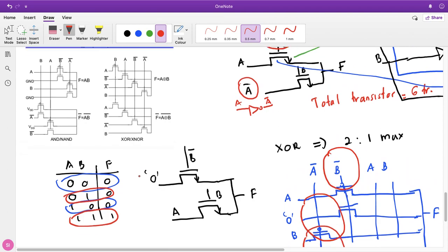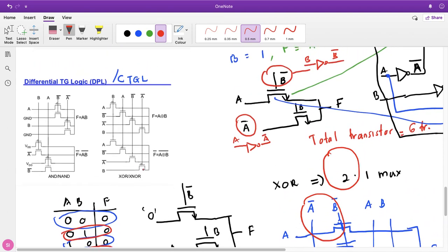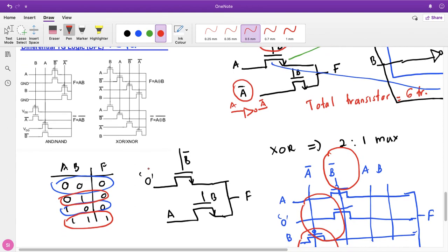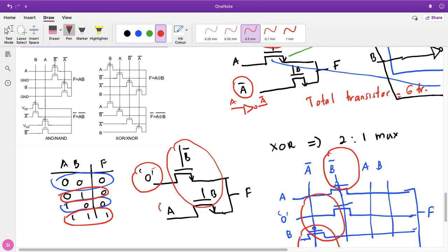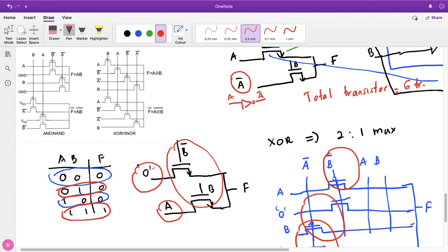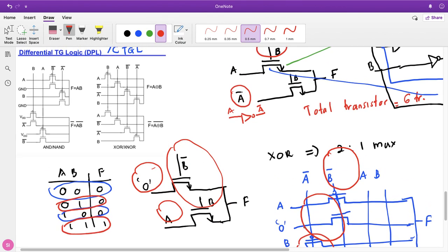Using the differential logic system is totally different compared with the CPL or pass transistor logic, because you must take note of all the information regarding the input, and not only use the one control line as the input, but use the input data to design the complementary transmission gate logic.